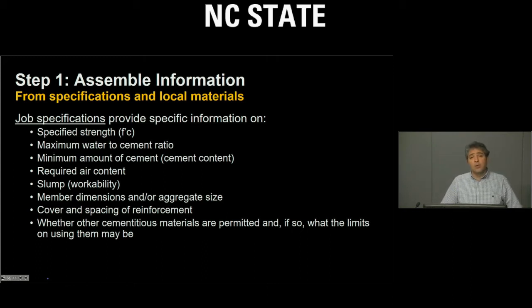And also, we want to make sure that we know whether any other supplementary cementitious materials such as fly ash and silica fume are allowed. Are there any limitations to the use of those supplementary cementitious materials? All of this information comes from the job specification.